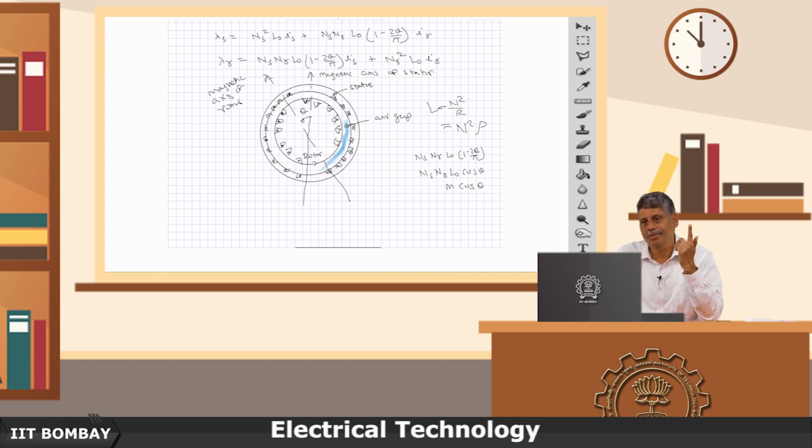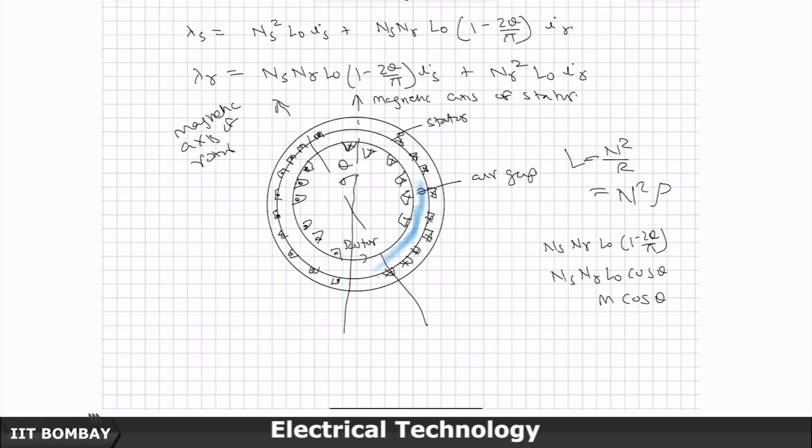I had said something about double frequency here, that is not correct, it is single frequency only, but now it is no more linear. At pi angle the mutual inductance becomes minus m, and then at 2 pi again it becomes plus m. So, you had plus m, minus m, plus m, but it was going like a triangle. We did not want this.